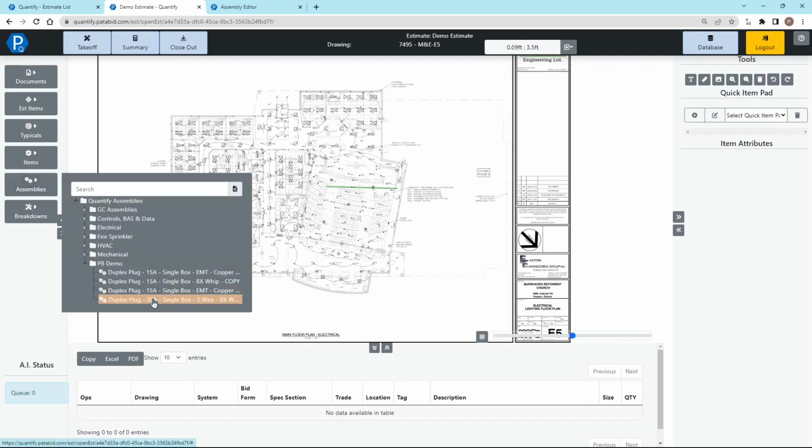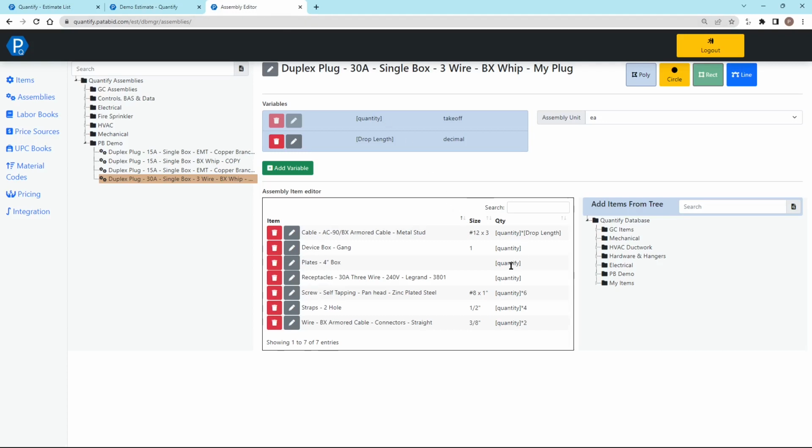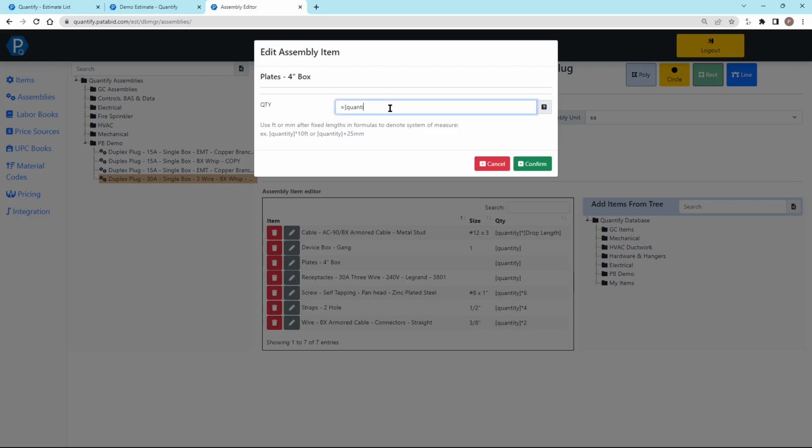When I go to take this off, I'm going to right click it, and it's going to give me an error. Because what I did is I didn't type quantity, I made a spelling mistake. I typed quantify instead. And the error will try to lead you in the right direction. So it says it's a parse error, column 0, it's an unknown character, and it tells you this is the problem. So we see, oh, quantify, that's not right. So when we come back here, we can check and say, there it is, that's the quantify one. I'm going to edit that and fix my spelling mistake.